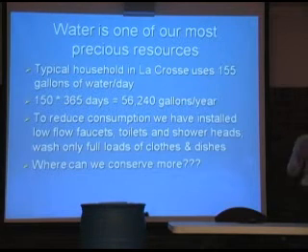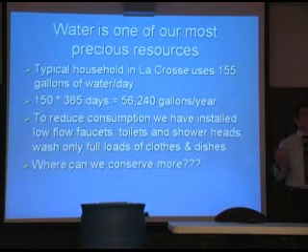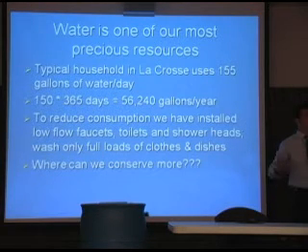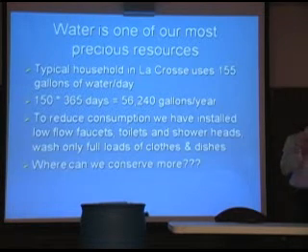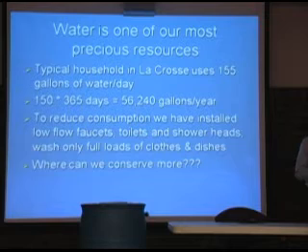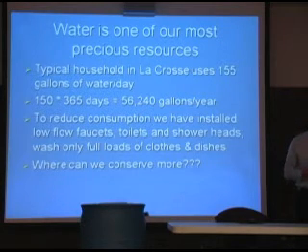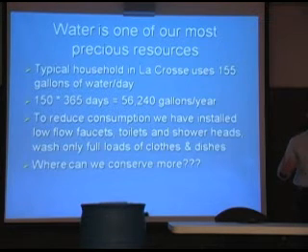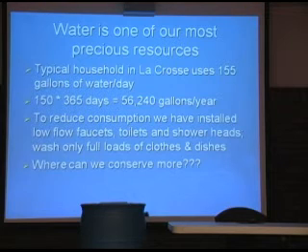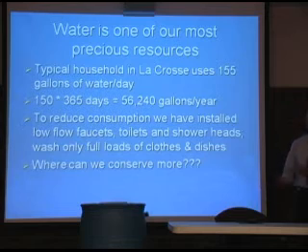So stormwater, why is stormwater an issue? It becomes an issue because of all the stuff that's in the streets that stormwater picks up. Rainwater typically is relatively clean, but once it starts hitting the streets and running over the oils and greases that are on the street, or the salts, or the pesticides, or just the grime or the sludge and stuff that just happens to be sitting on the ground, it picks all that stuff up, and eventually it just brings it right to the river without any sort of treatment.